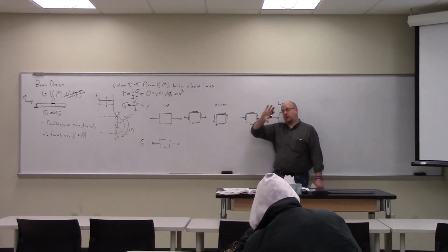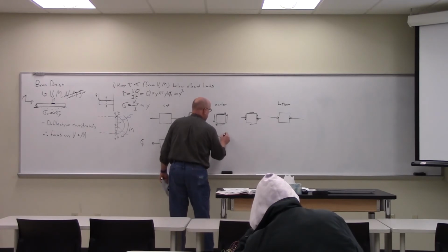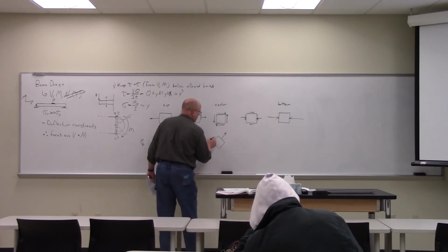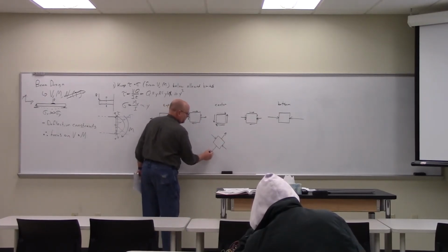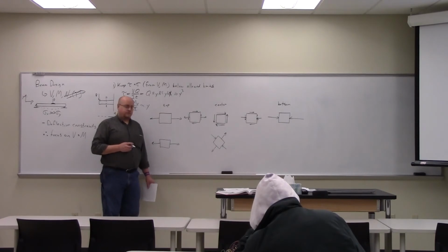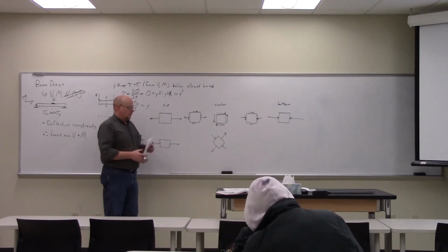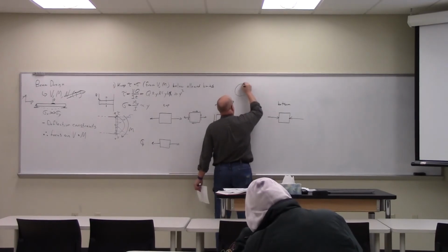Because you're rotating the Mohr circle by 2 theta p. So theta p is 45 degrees. So here, those are supposed to be roughly the same length as the shear stress, like you said. Why do you have 4 vectors instead of just 2? Let's think of it in terms of the Mohr circle.